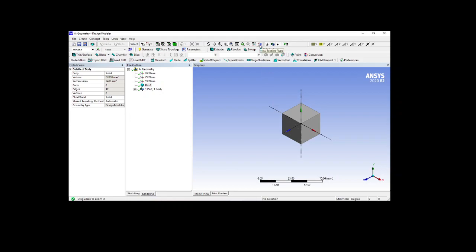Next, come to the new section plane. New section plane helps us to analyze each individual part by cutting the geometry. I will press it and you will see a detail window. I will keep it here so that I can better visualize. I will create one section, so I will right click here, left click here. Next come to here, so I will unpress it so I will understand. Is there any activation? No. Come here and I have activated this new section plane.